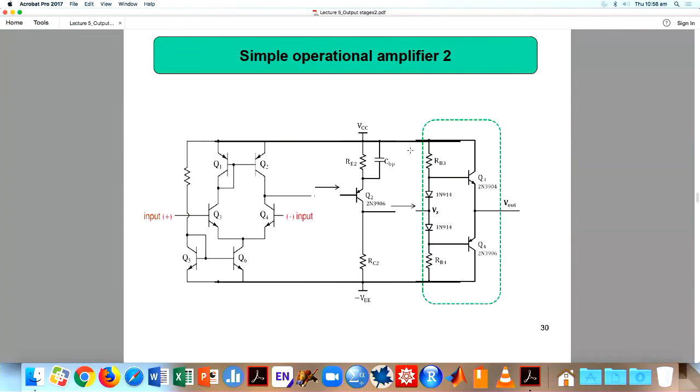If you want to design something a bit more sophisticated, you take your differential amplifier, then connect maybe another PNP amplifier. Why a PNP amplifier? Because you get some voltage level shifting if required. Or you can connect an NPN amplifier. Then you connect to your output stage. When you do this, you have already designed an operation amplifier. You know what I mean? So I would say this is a basic operation amplifier. That's how we design an operation amplifier. Simple. Now we can increase the complexity.